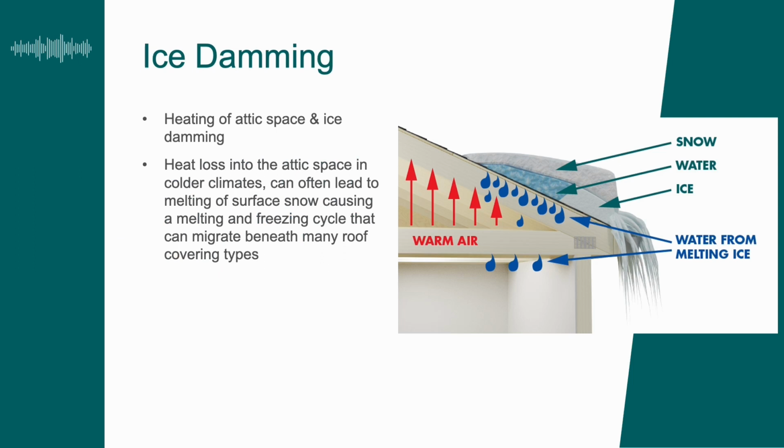A big reason to consider secondary water barriers is related to ice damming. There are some areas in Texas that you're going to have it, and throughout climate zones 5, 6, and 7, you're not going to see a lot of it in 4 and below for the most part. It'll be an unusual condition. But ice damming is a real condition that creates a lot of damage in a lot of areas, especially in roof coverings, because most of our steep slopes are not interlocking systems.